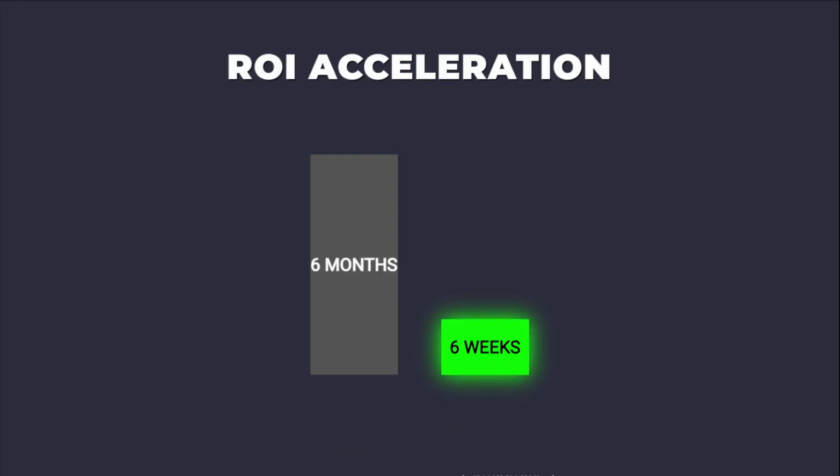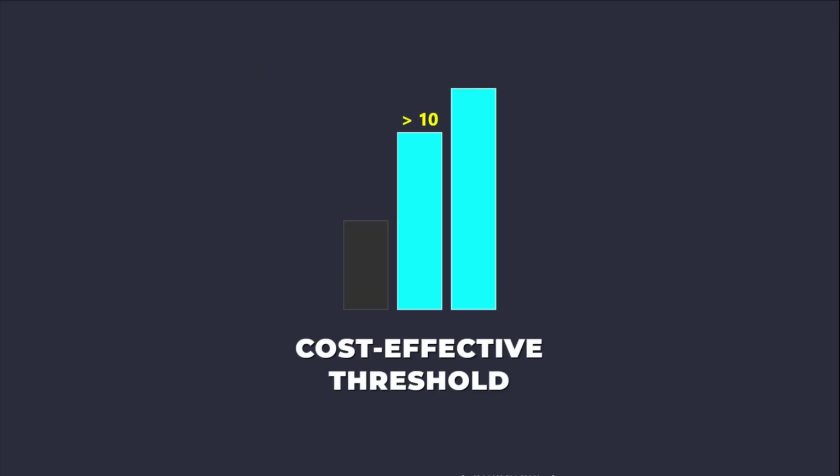The economic justification for implosion rests on time savings and reduced labor costs compared to mechanical demolition. A large structure that might take 6 months to dismantle conventionally can be imploded and cleared in 6 weeks. While the upfront cost of explosives, specialized labor, and permitting is high, the reduction in site occupation time significantly lowers overhead and accelerates the client's return on investment for the new construction phase.